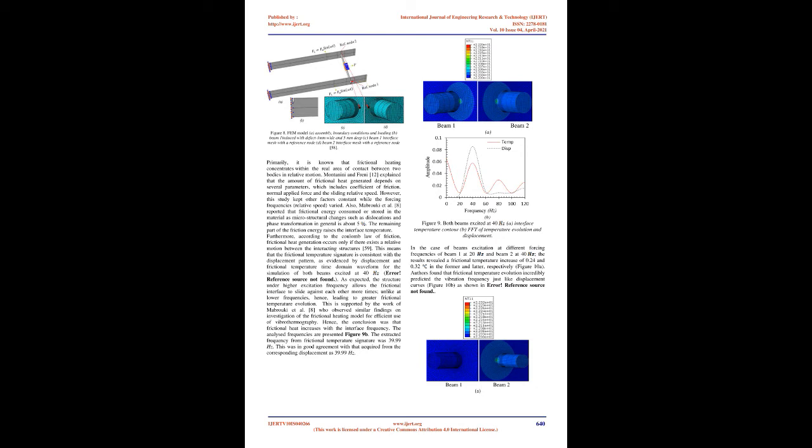Spiderbox X80 vibration controller, operated by PC2, firstly generated the required signals through outputs 1 and 2 for the vibration shakers attached to beam 1, Bruel and Kjaer, model 4824, and beam 2, Centec, model MS1000, respectively. The signal for the former was amplified by a Bruel and Kjaer model 2732 amplifier, while the latter by a Centec model LA1500 amplifier. These facilitated the beams' mechanical excitation.